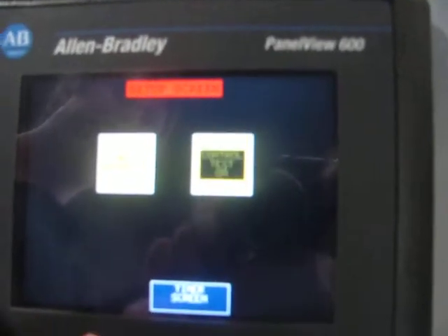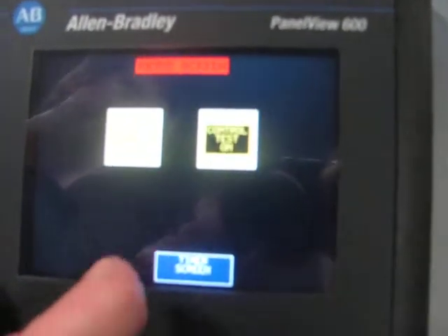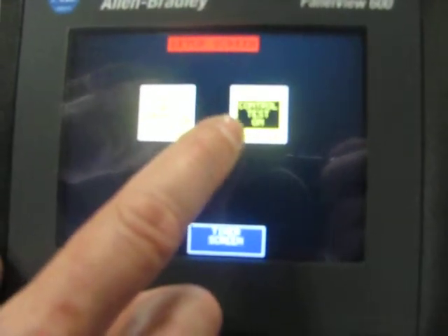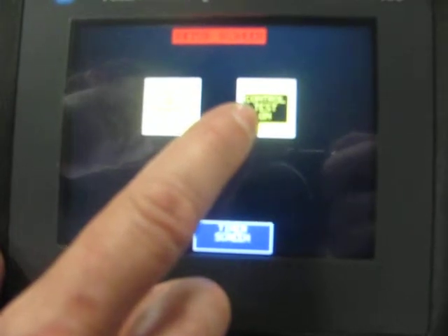One more time. If you press the control test button, you'll see it'll flash. This is to let you know that this is not normal operating conditions. If you press this button and you leave it like this, when you run an RF cycle, only the timers will run, but you will not have RF. Similar to the heat seal cycle.